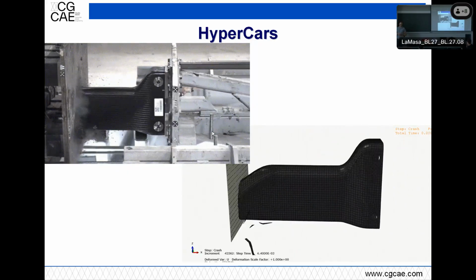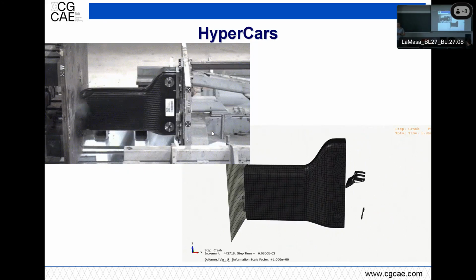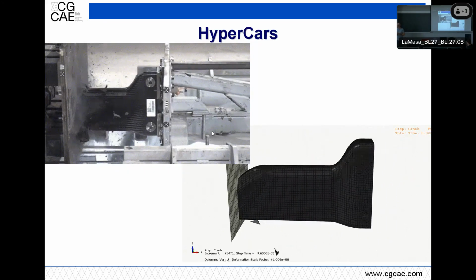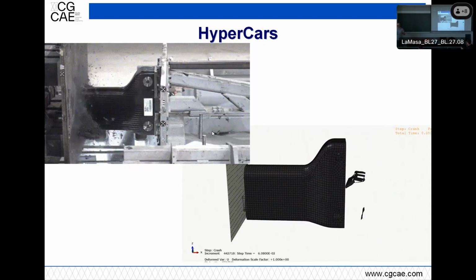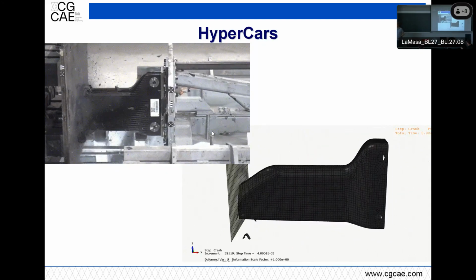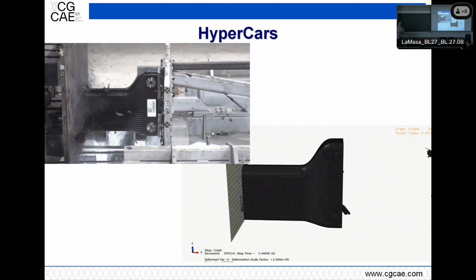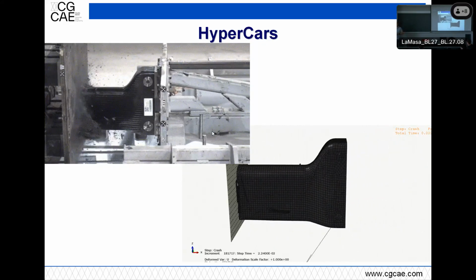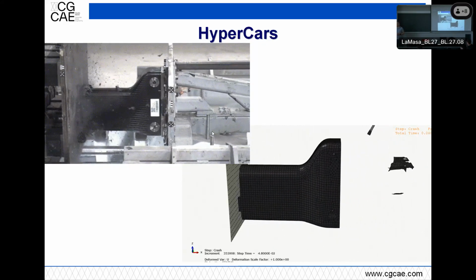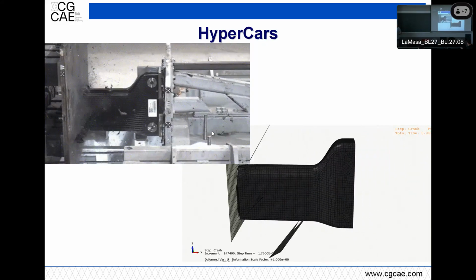Monte Carlo had special wishbones, especially for the steering rod. You made a high steering angle, so this was changing. And you had a reinforced steering rod and track rod at the rear because hitting the barrier was more common than on other tracks. In more recent times, we based it again on some assumptions, reducing the design loads, and you do the calculation like that.